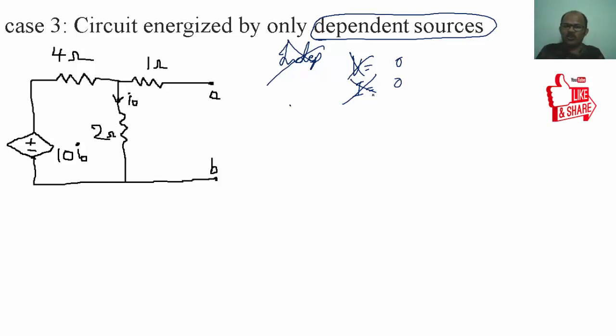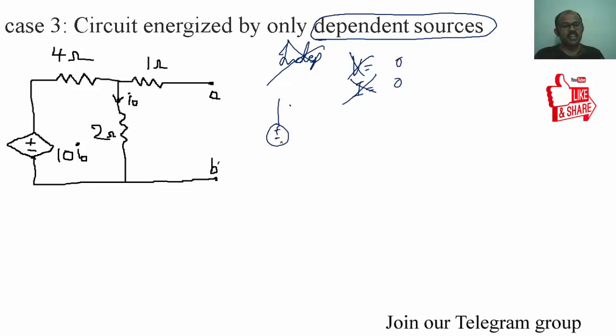So in order to calculate the Thevenin impedance, you are going to make use of a test circuit across the terminals A and B. If you are using a voltage source, you provide 1 volt. You can give 10 volts or 100 volts also, and based on that the current will also vary. For my convenience, I have taken 1 volt, or you can inject even 1 ampere of current. Either one of the cases you can do.